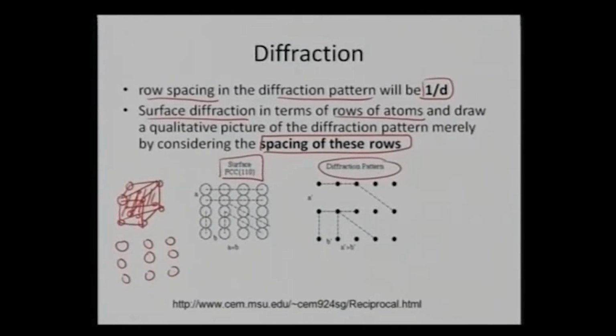I will get some sort of a construction where these atoms are much closer as compared to these particular atoms. So that is what we are seeing here, that in this particular case we have A less than B. It means I can even have the atoms touching one another, or they can have spacing much smaller than that of B. So my interplanar spacing along B is much more scarce, spread quite far apart in comparison to my lattice spacing along this particular A direction.